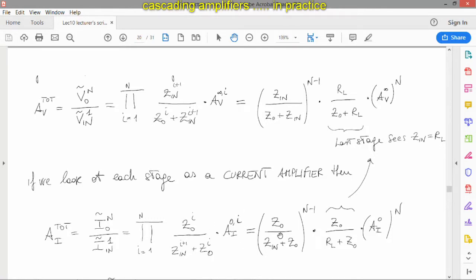Remember, you need to choose the capacitors in such a way that for the frequency you are interested in, these capacitors effectively have an impedance that is effectively zero. What zero means, I discussed last week in the post-lecture video.